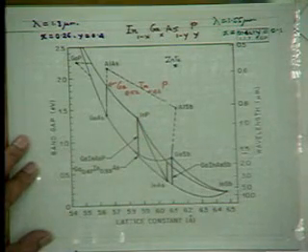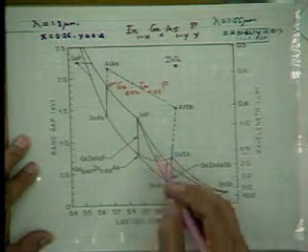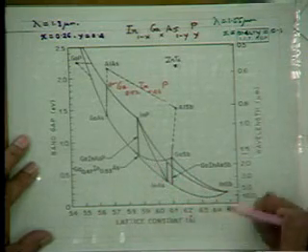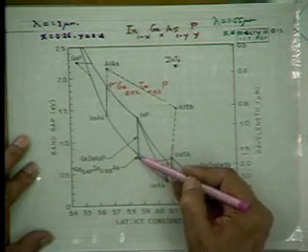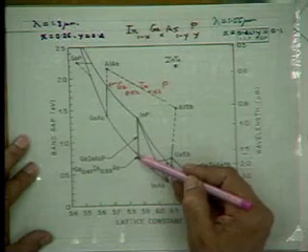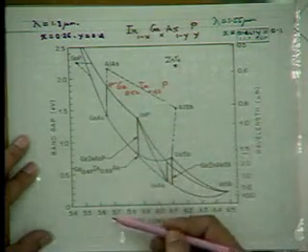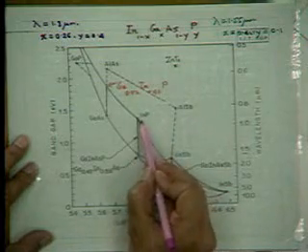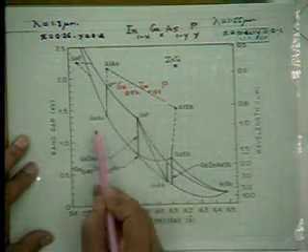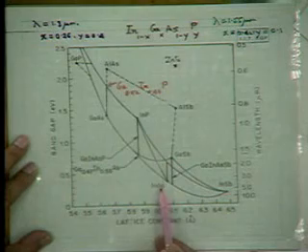I'll discuss the importance of lattice constant as I go along. For growing epitaxial single crystal layers, the grown layers, the thin layers, have to have the same lattice constant as the substrates. And the substrates that are available are binary substrates such as indium phosphide, gallium arsenide, indium arsenide, etc.